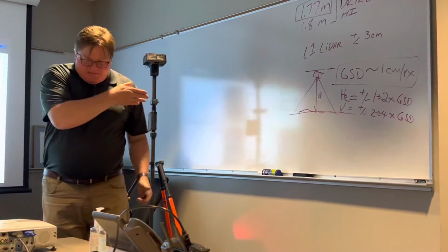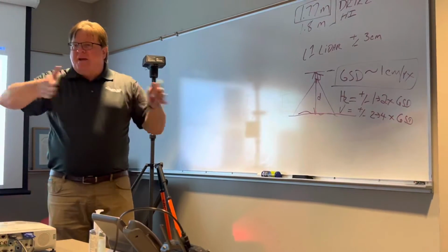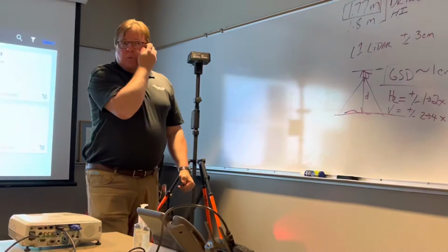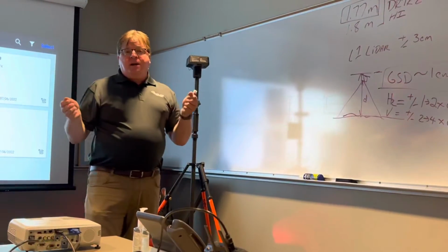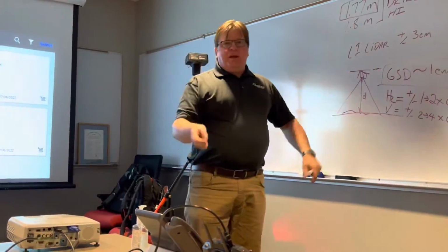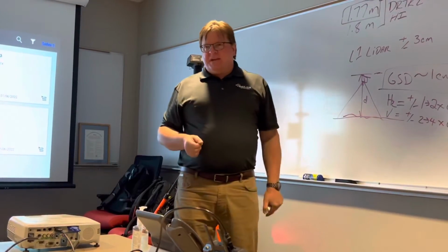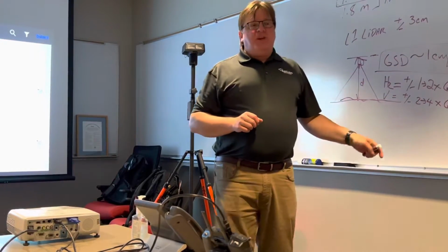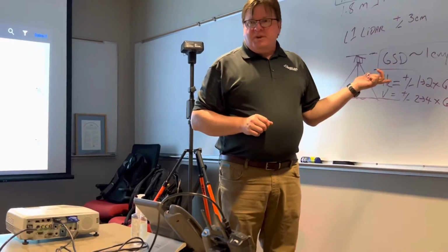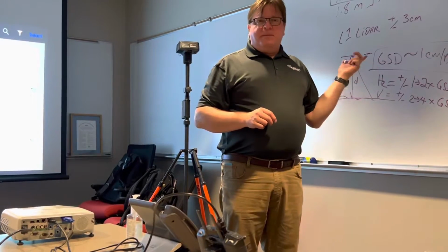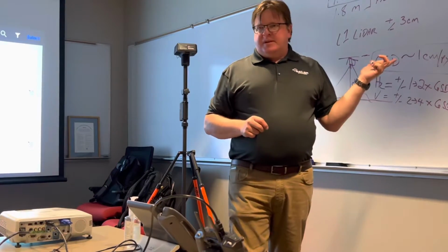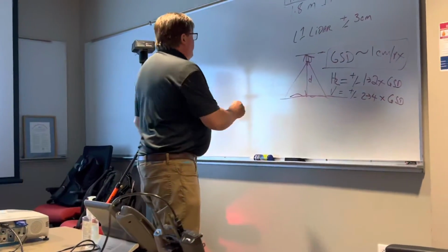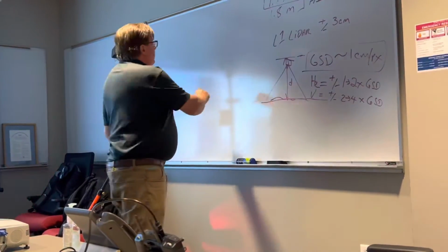So it's shooting LiDAR at a fixed pattern, and the forward motion of the drone carries that density with it. You'll see as we make models, when we make our photogrammetry model, at the very top of the page, it's going to calculate our ground sampling distance, or GSD number, for us and tell us where we're shooting at. I guarantee you, if you bring that mission at 260 feet, it's going to be 0.99 centimeters per pixel every time, regardless.